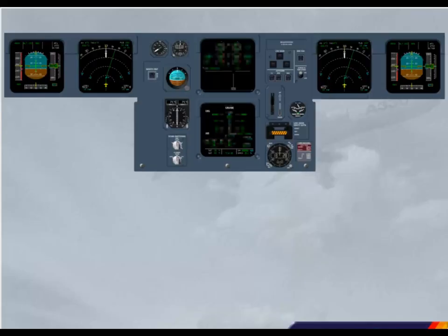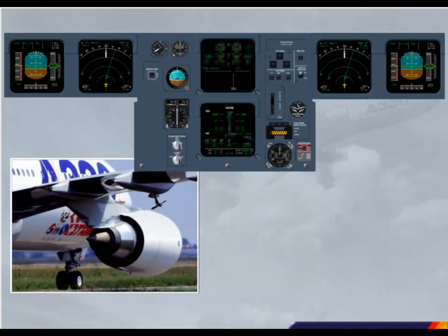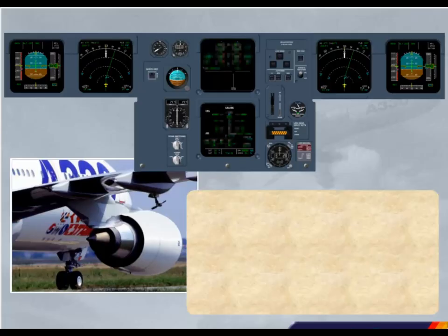We will now study the electrical emergency configuration. We will demonstrate the case when the system is powered from the RAT. For that, we will assume that the green hydraulic circuit is already faulty. Note, if the green hydraulic system, which actuates the emergency generator, was supplied by an engine-driven pump instead of the RAT, more electrical power would have been available. This limited amount of power will lead to the shedding of some equipment or electrical buses.